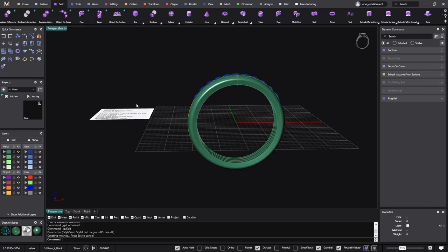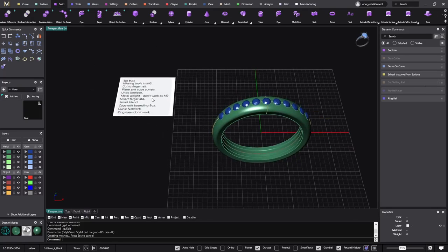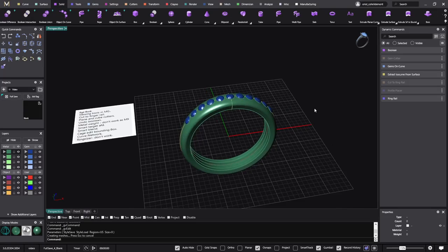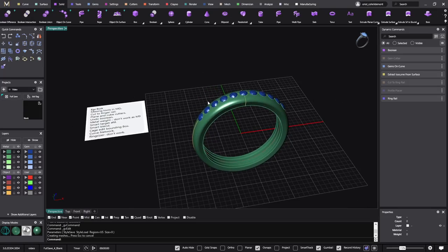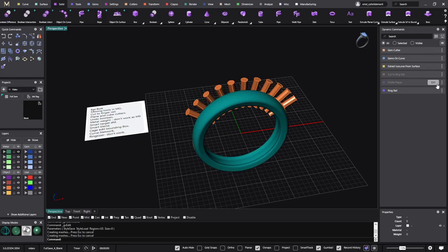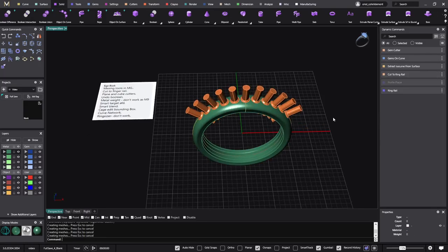So you keep the objects that have been in this Boolean. This is important to know. We don't need the undo Boolean because this software is parametric and we keep everything that has been used in this Boolean. So now I can go to delete Boolean, but the only thing I need to do is just show and show, and we have them back here.